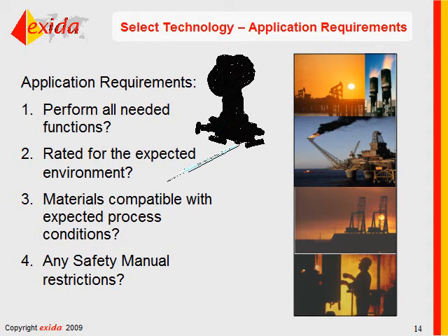I know it's more tricky in terms of level meters and flow meters because there are many different ways to measure levels and flows. You must pick the instruments that will actually do the job. You must pick instruments that are rated for the expected environment. You must pick instruments that are compatible with expected process materials and process conditions.